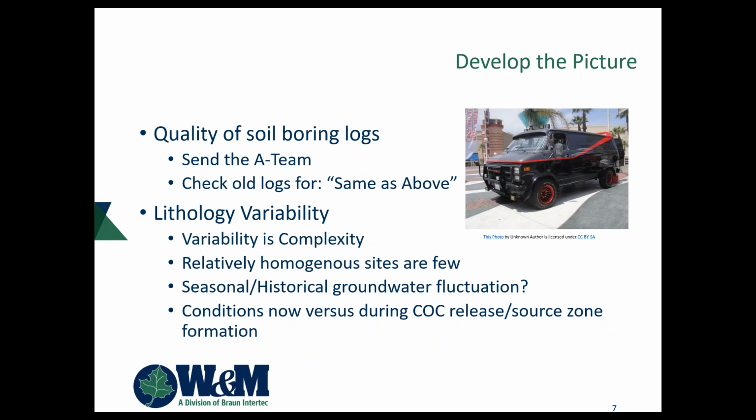borings right. So I guess the point here is we really want to see a high level of detail in soil boring logs that are going to be interpreted for remediation planning. Send some senior folks out there, and try to send the same folks every time, so there's a whole lot of consistency in what's being put on the logs.